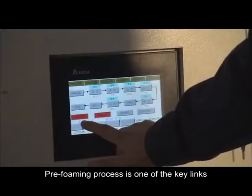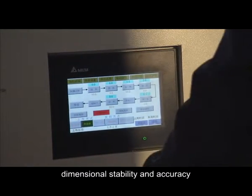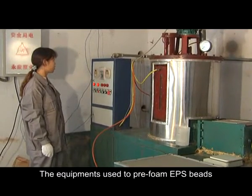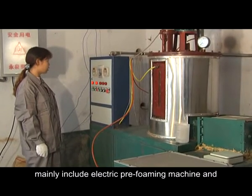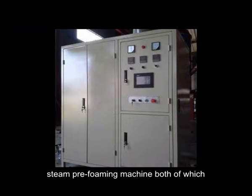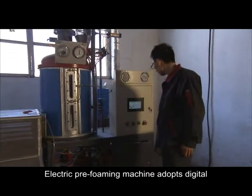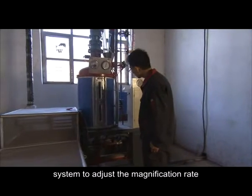Preforming process is one of the key links which determine the model's density, dimensional stability, and accuracy. The equipment used to preform EPS beads mainly includes 2 kinds: electric preforming machine and steam preforming machine, both of which use the most advanced PLC technology. Electric preforming machine adopts digital system to adjust the magnification rate.